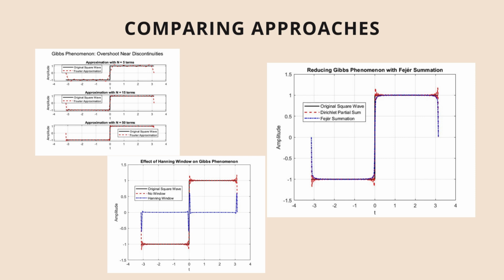While Fejér summation doesn't eliminate all issues in the sense of producing a perfect step transition, no finite sum of sinusoids can truly jump instantly. It offers a more controlled, smoother approximation. Practically, this is very valuable in DSP tasks, where sharp transitions cause unwanted ringing in filters or reconstructed signals.